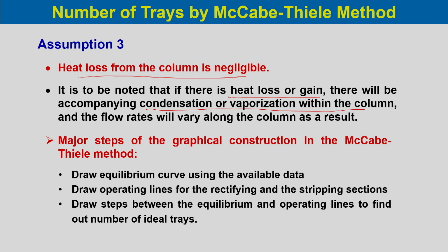This graphical method of finding out the number of ideal trays required, we will discuss later. But we will go systematically to find out the operating line equation and operating line for the stripping section and the rectifying section. We will discuss that part first.